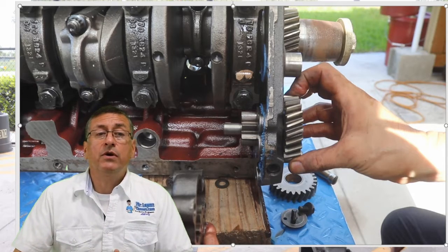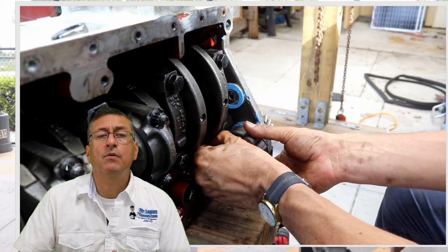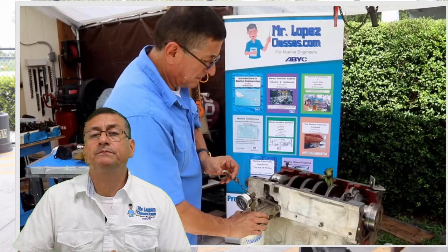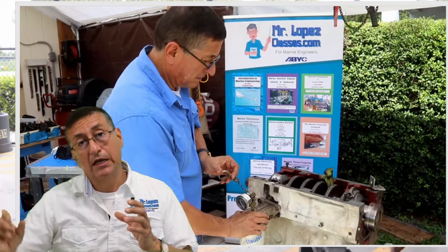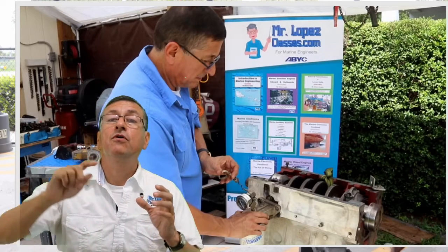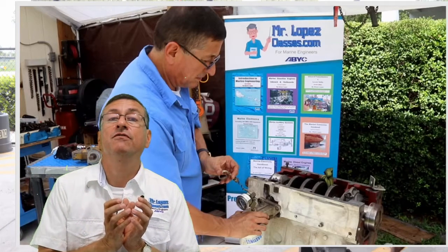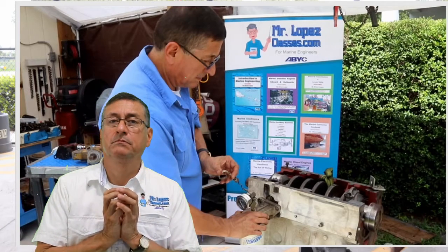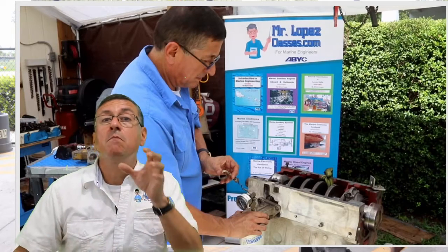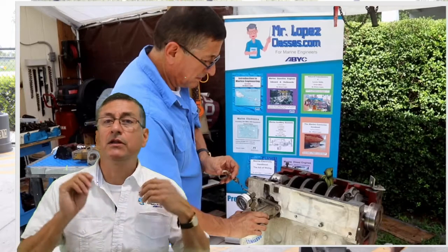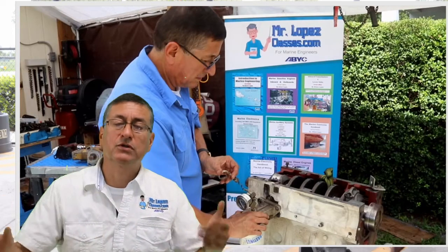All right, my friend. Right now we remove the oil pump, and this is the moment to verify. The oil pump sucks the oil and sends it into the block. Before the oil enters the block to circulate, the oil passes through the oil filter, and of course the oil filter is located in a bracket bolted on one side of the block. This is the element that you replace in the service. When you replace the oil, normally you replace the filter, of course, and replace the oil.